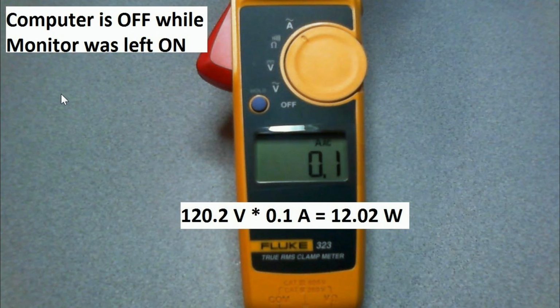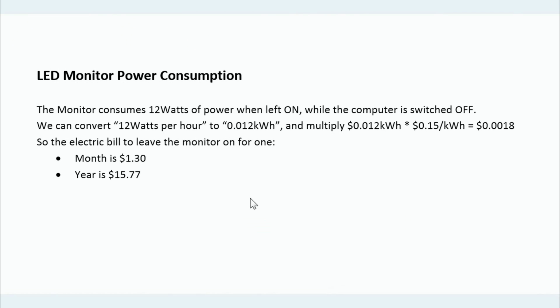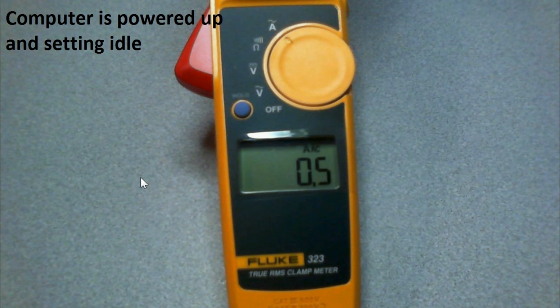With the computer turned off and the monitor left on, the monitor consumes around 12 watts. So let's calculate what that would cost. If we take our 12 watts per hour and convert it to kilowatt hours, and then multiply that by the 15 cents per kilowatt hour, that gives us about 0.0018 cents per hour. The computer is powered up and sitting idle, and it's consuming the same amount as a 60-watt light bulb.